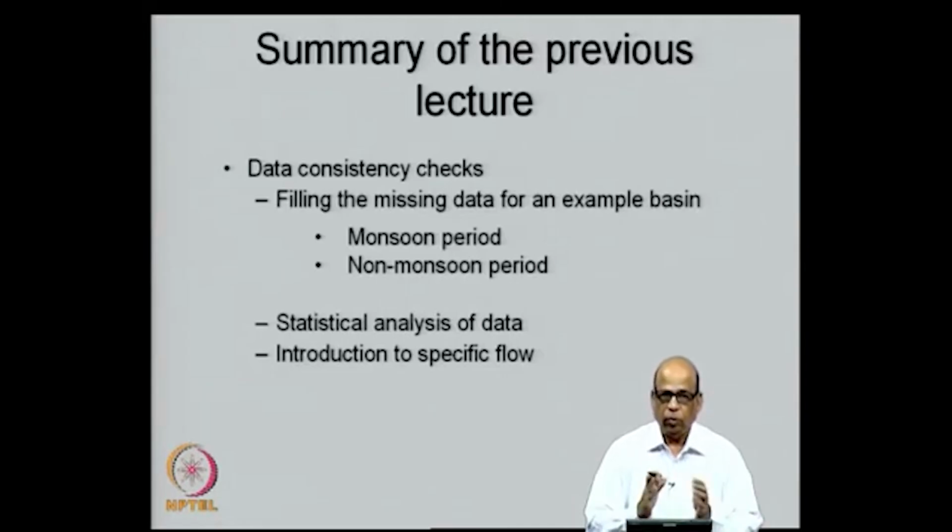We typically used two different periods. For example, for the monsoon period we adopt a certain procedure, and for the non-monsoon period, where the flows are very small in the peninsular region, the flows are essentially due to the base flow. So, we adopt different procedures for the monsoon periods as well as non-monsoon periods for filling up the data.